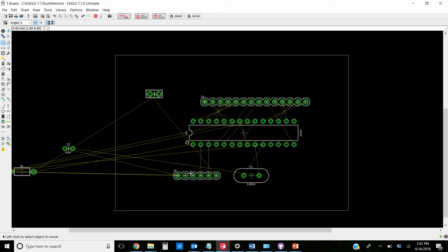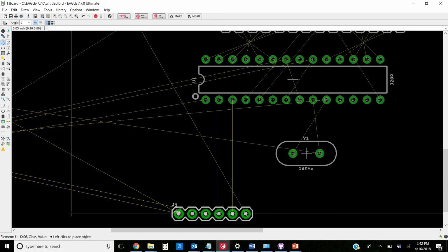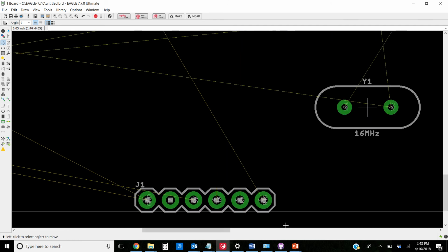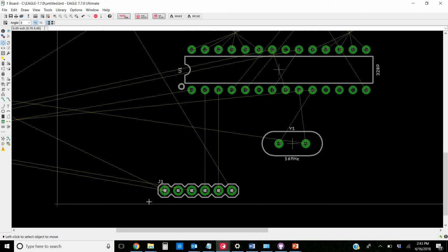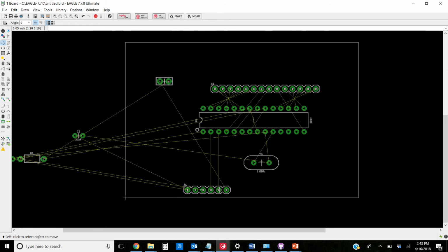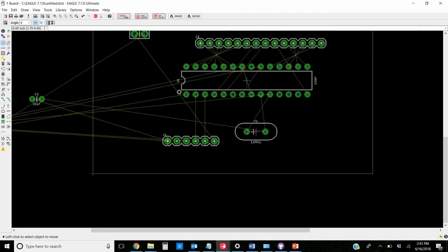All right. The other thing to consider here is when we're fabricating the board, we don't want to get these right on the edge here, right bumped up like this. That's pretty close to the edge of the board. We're going to want a little bit of room when they fabricate these things. They're going to route or sometimes crack the board from the next board, and if we have it too close, it can sometimes cause some issues. So we want to keep a little bit of a border all the way around this thing. But in this case, we've got plenty of room, so we're just going to move that up. And again, we'll uncross these and give a little bit of room there.